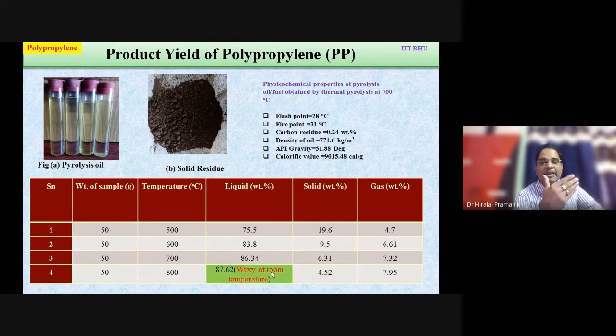When we increase the temperature, the product formed from the big polymer polyethylene undergoes secondary reactions, and further cracking takes place. The larger molecules do not get time to stay in the reactor for further cracking because of the high temperature, so they immediately escape. At lower temperature they get time for further conversion.